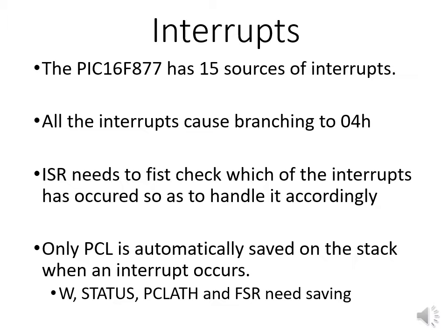Registers that need saving are the working register, the status register, the PCLATH register, and the FSR register. These registers can potentially be changed by the interrupt service routine. And when they are changed, they will cause the operation of the PIC to deviate from what is intended after return from the interrupt service routine.